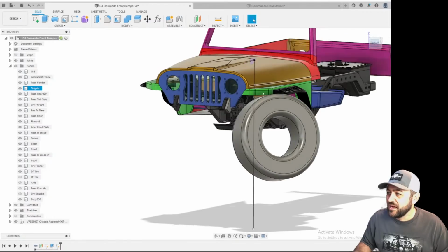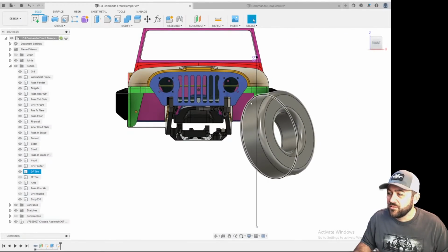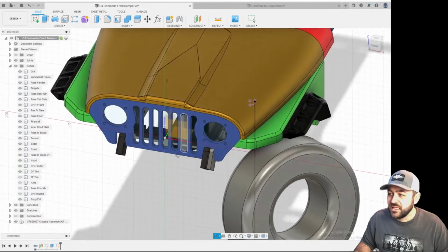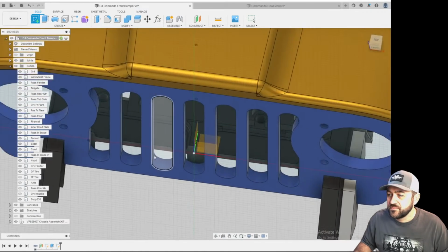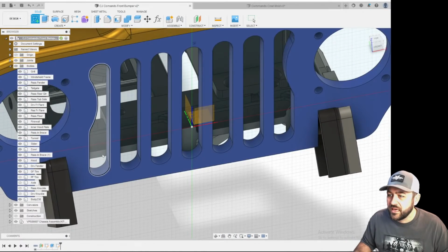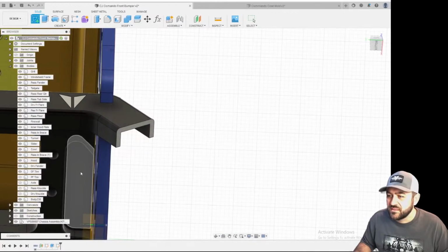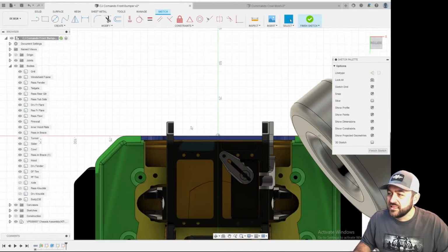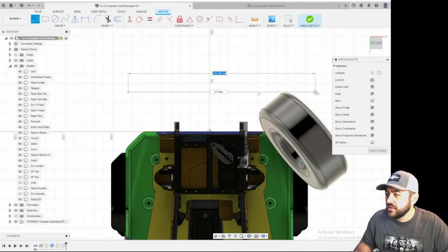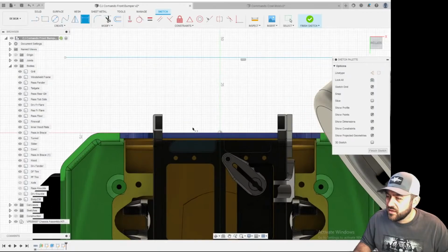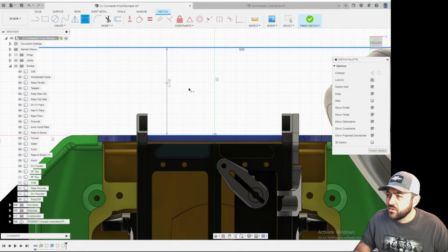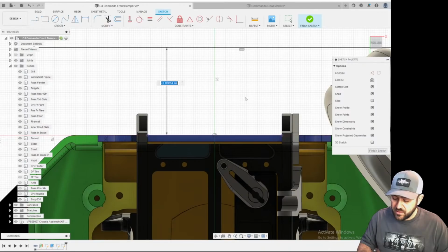So I created that line, which is just going to hang out there. That's the widest point of my windshield. Now I also need that one that we just discussed, which was how far it needs to stick out. So I'm just going to grab a horizontal surface somewhere up near here. How about that one? And I'm going to make that line that sticks basically 1 inch forward of the grill, which is a ways, not that far, thankfully.